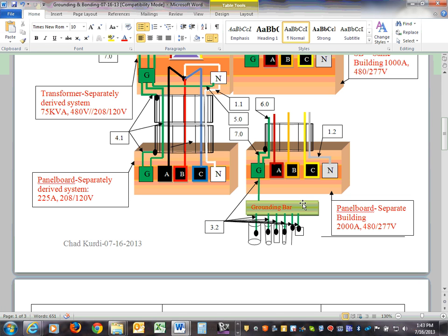We've seen buildings with a 500 kcmil copper ground ring around the whole building, tied from every side to the rebars of the concrete building or the steel if it's a steel building, and then the whole service is bonded together. Then you can tie to anywhere in the service and have the same potential. So, any comments, guys?